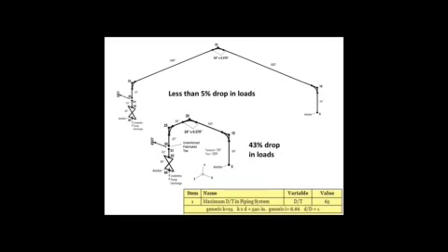Okay. This one doesn't have sound on it, so I can add something to this slide. What happens here in this example is that the D over T ratio is high. D over T ratio is high, piping is short, so loads through the run materially affected the pump loads. So we didn't worry about the branch.